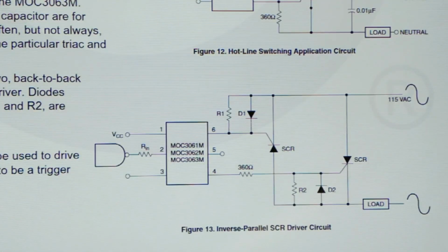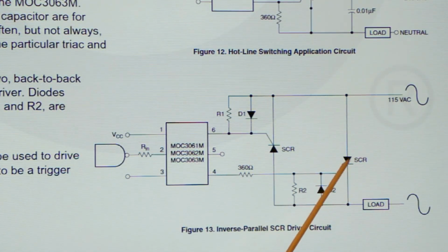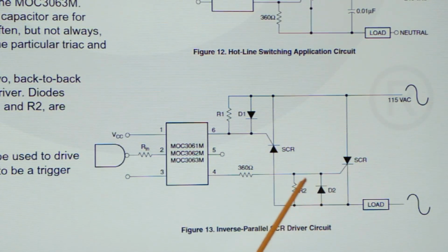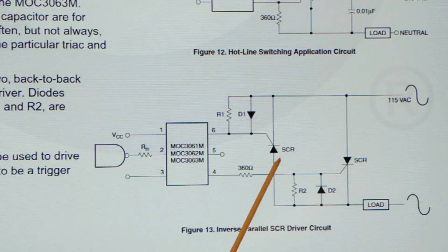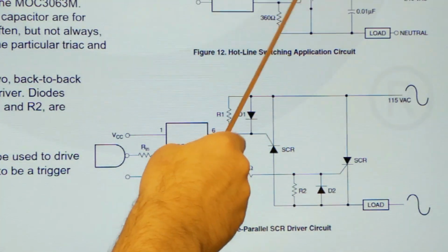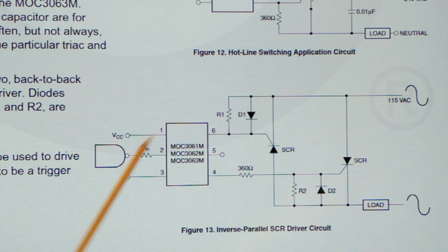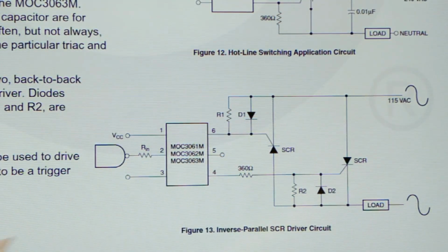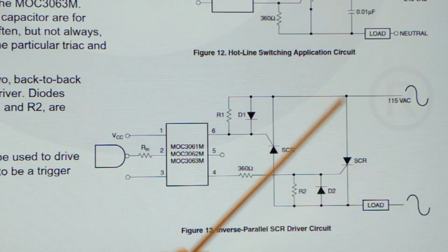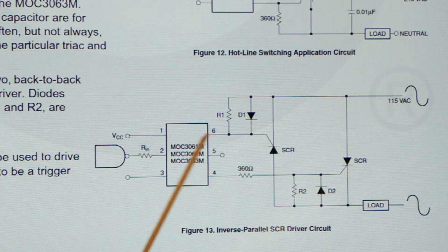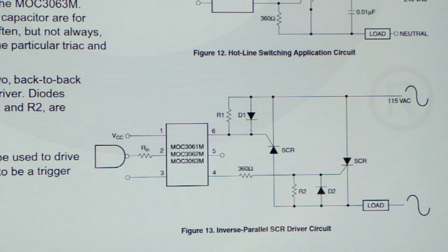But one thing I do know is that this is good. If there's ever a short circuit, this is going to be able to handle the short circuit, 100 times better than that. In a short circuit, that's probably going to blow up. In this case, it will not. I've got the fuse, and the fuse should blow first, the 8 amp fuse.